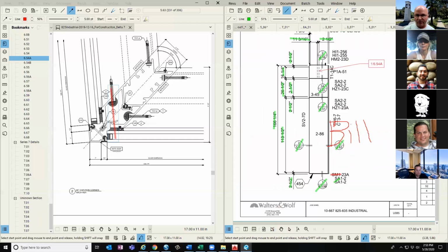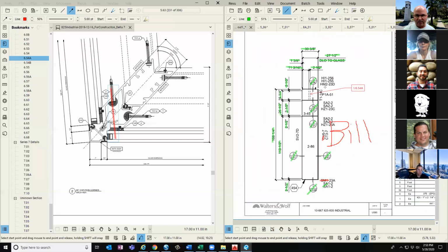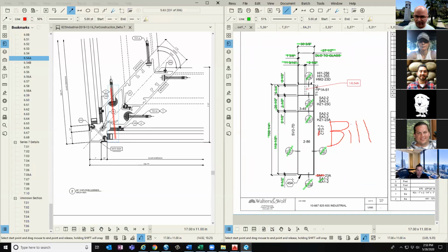So as I finish those, I'll look to see if there's other notes on here. There's a gasket showing on the bottom. I want to see if there's any gaskets that are showing on the unit assembly drawing. I want to see, are there added notes that the shop needs? Do we need to give them an index on how parts are adjusted next to each other? So I'm going to look at this in even more detail. What we've reviewed so far is just mathematically checking.